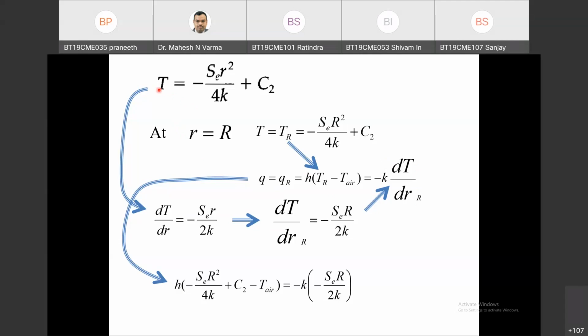So this temperature profile is true till R equals capital R. That is what I am using. This dT by dr is true only up to R equals capital R, and I am taking the value at R equals capital R only, not greater than this. I have substituted R equals capital R and then substituted here. So this is kind of using the flux profile. You can use that flux profile directly and keep R equals capital R. You will get the same thing.